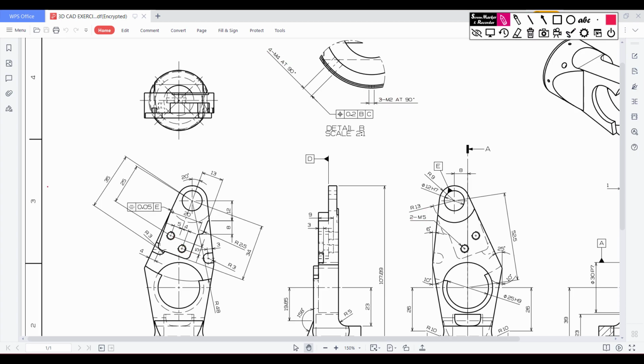Let me now see, we have 2 extrude cut circles here and they both are M5. So I'll use a 5 radius circle instead. In the dimension here we can see the first circle has a distance of 25 unit and a distance of 5 unit, and the second circle has a distance of 4 unit and a distance of 5 unit. So I'm going to sketch here now.